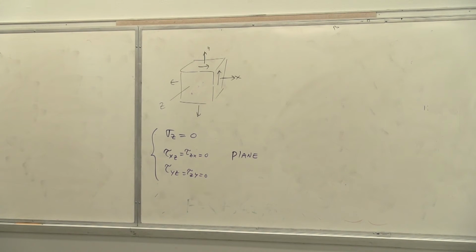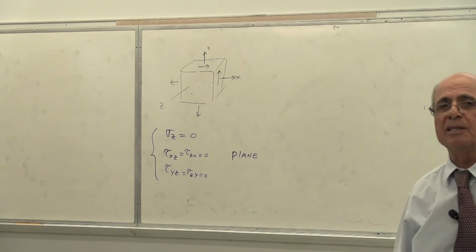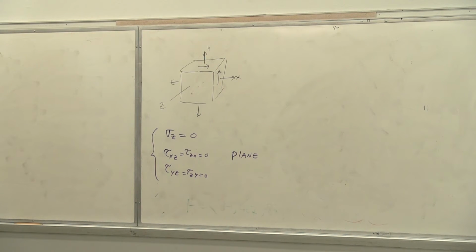In other words, if the airplane is sitting on the ground, you can design it because when you look at the body of the airplane, there is nothing coming from the air side except air pressure, yes or no? However, if this airplane goes to the sky, that's not the case. Everybody knows that. There are going to be forces there. Is that correct? It is no longer a plane stress scenario. Everybody understand what I'm saying there? Yes? Or you put an object on the bottom of the ocean, designed like a submarine part or pipe, there is sigma coming from all different sides. Is that correct or not?